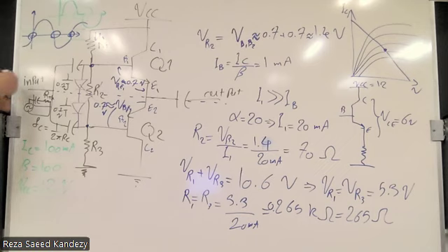But you need to have an untouched AC signal when it comes to the circuit. If you have a 1 kilohertz signal, which is normally around that, normally your input signal is high frequency. So if you have a high frequency signal, then you have the freedom to choose that cutoff frequency somewhere around 100 hertz.